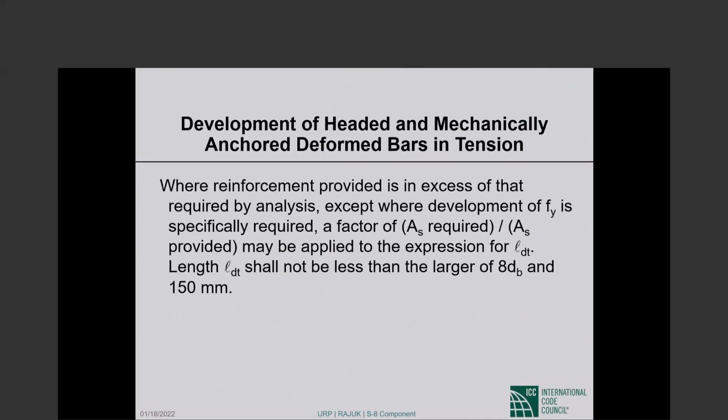A factor As required over As provided may be applied to the expression for L sub dt. Length L sub dt shall not be less than the larger of 8 bar diameters and 6 inches.